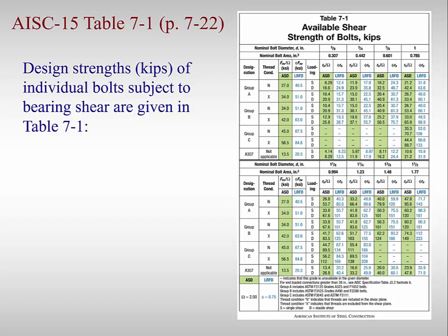As previously mentioned, the common diameters for structural steel are 3/4 and 7/8 inch diameters. You can make use of this table in this class to get your shear design values for bolts. You do not need to use the formula previously shown unless specifically asked to do so.